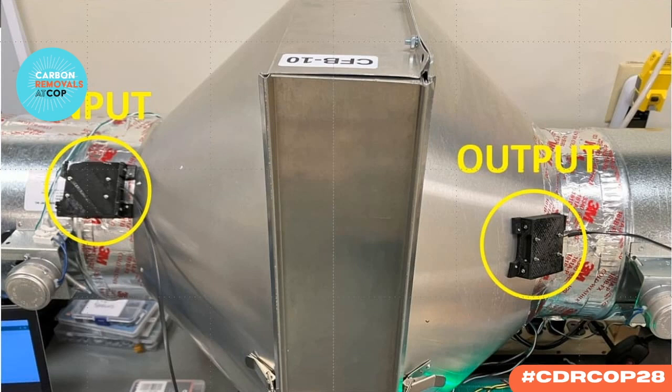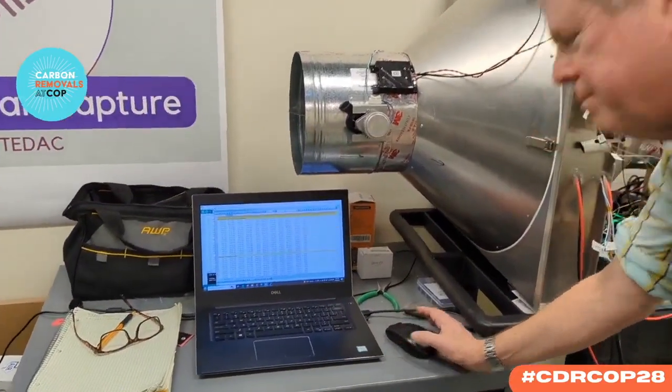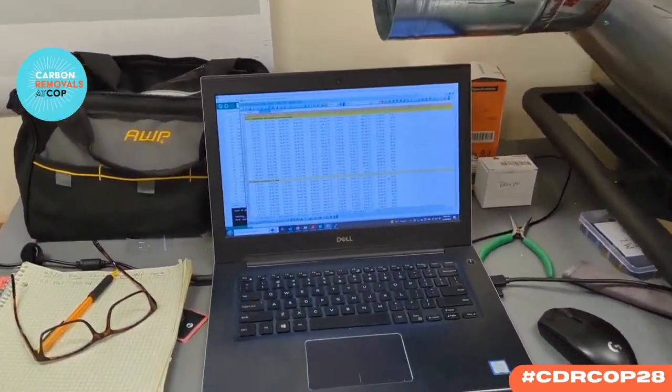There you go. And while you're adsorbing it, you should be able to measure that the CO2 on the output side is less than on the input, which would mean the sorbent is actually capturing CO2. And then in the desorption phase, you can measure the CO2 that's being released. So you can calculate how much you've actually captured and released. I think I have some images of that here, David, I believe. Is that what we were capturing here?